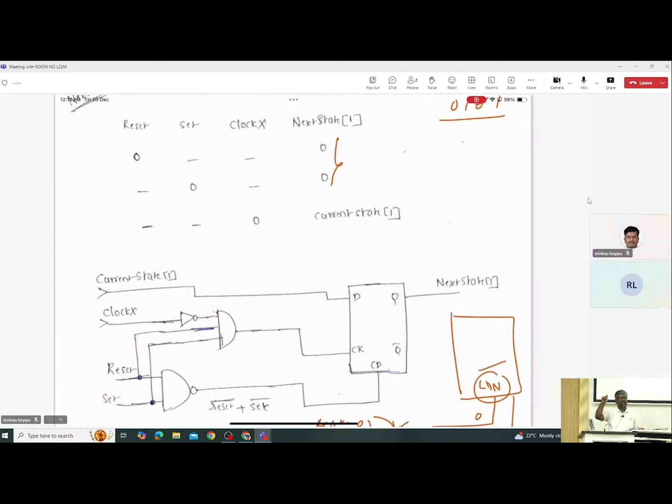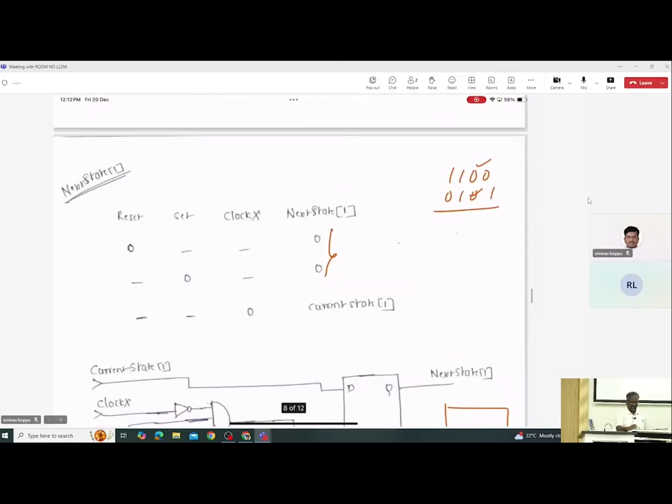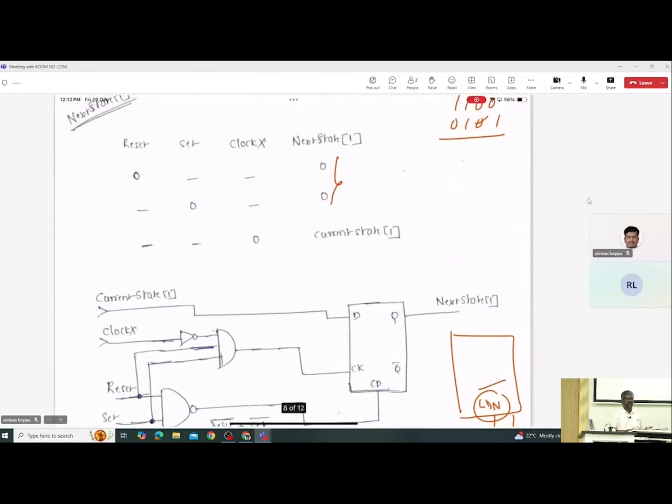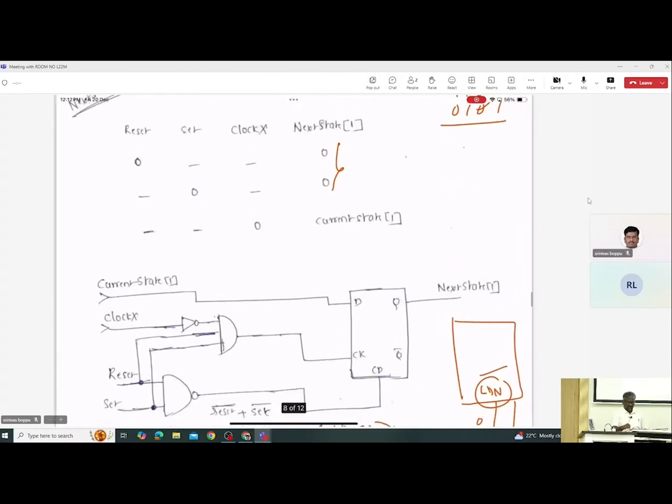So in both cases it's connected to a reset or a set, and both are 00, right? So that's what we have. Now what he's trying to do is map both of these cases to the CD pin, but the CD pin is an active high pin. It's not an active low pin.